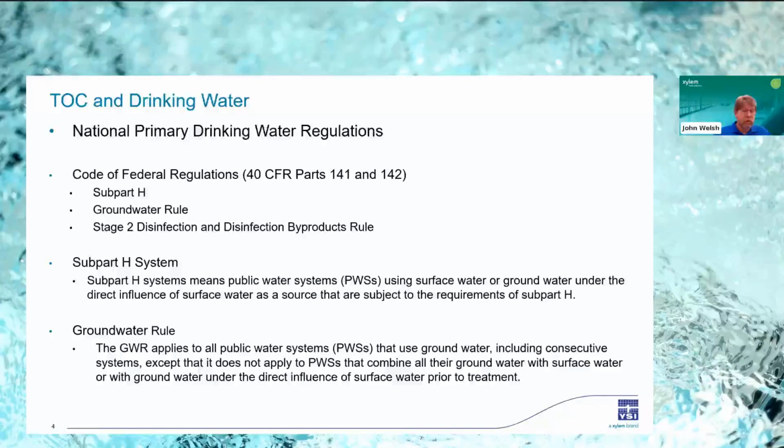For instance, the Safe Drinking Water Act gave us the disinfection byproduct rule, among other things. NPDES gave us BOD, COD, or TOC determination in wastewater. The RCRA gave us standard method 846 for monitoring wells around landfills and other contaminated sites.